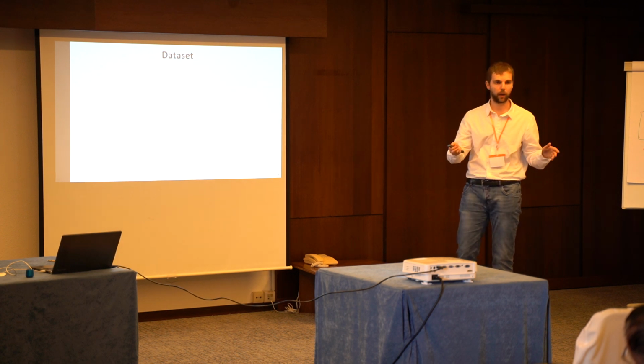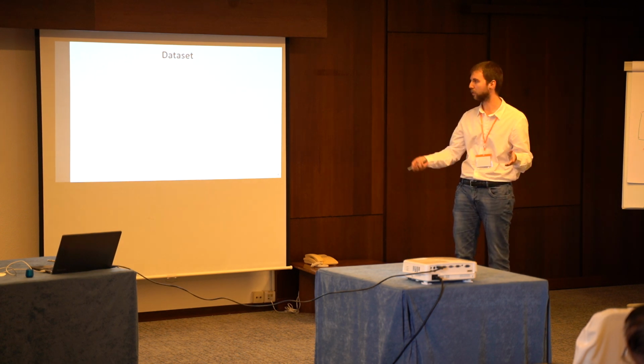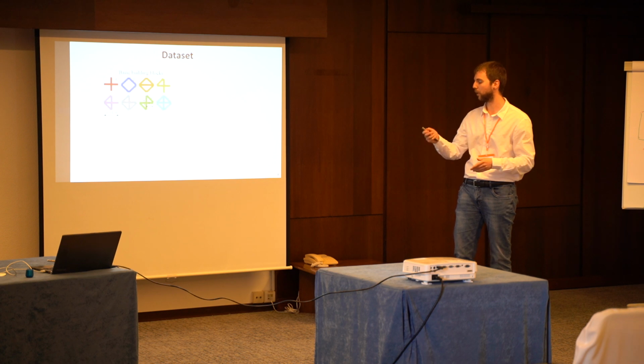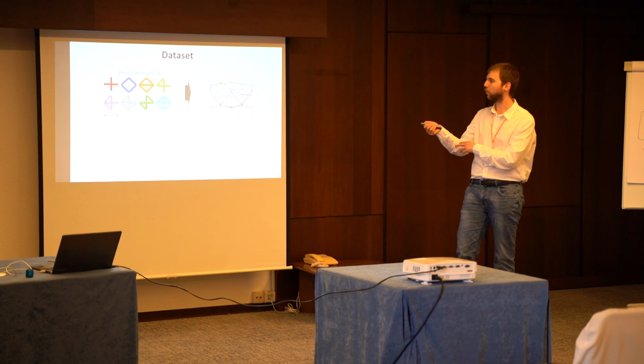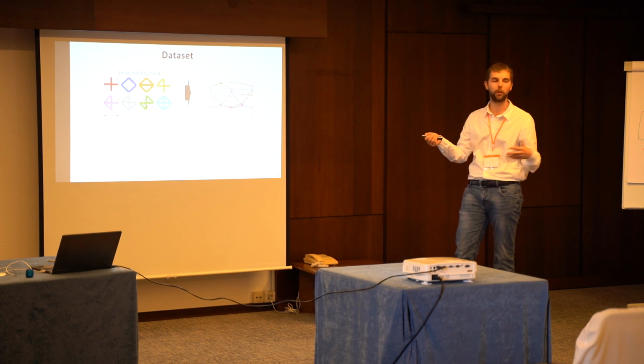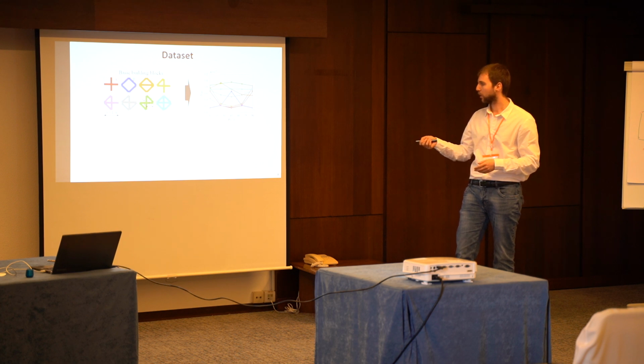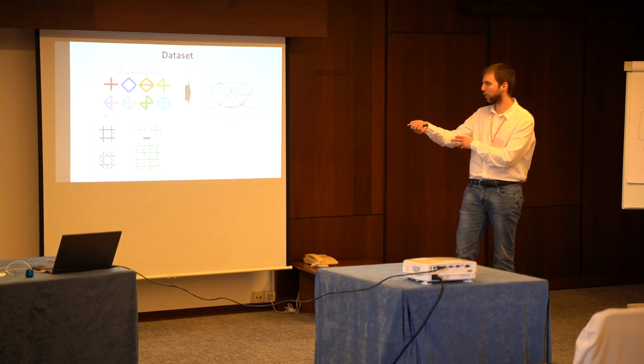So our goal is inverse design, so we have to create datasets before. We start from the basic building blocks, and then evaluate the buckling strength by simulations along different loading directions for each building block. We can choose which building blocks to combine. Of course, this is an arbitrary choice. In our case, we combine these two previous building blocks that I've already shown, and we create more complex unit cells.